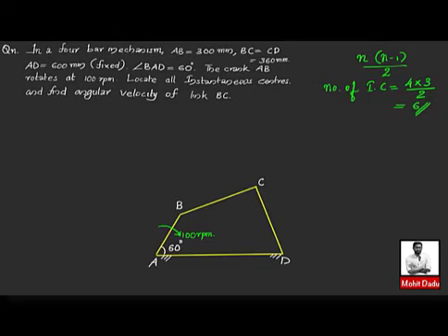Next step, we will be naming all the instantaneous centers. They can be named in such a way that, 4 number of links are there. So I will be writing the first link, and it can make combinations with the other 3 links. That is I12, I13, I14. Next I will be taking the second link. This can make combination with the other 3 links. So I21, already we have written the I12, so I21 will not be there, I22 will not be there, then you have I23 and I24.